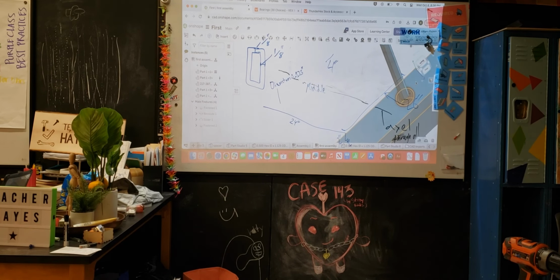To get the slider mate to work, if you look up here at the icon, you'll see these two black lines. That means that you want to work with edges. I remember now. If you work with faces, the way it defaults is that if you click a face, it'll move perpendicular, so they'll come apart and go through each other.